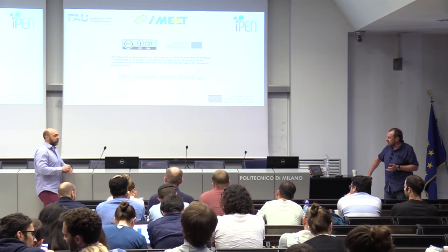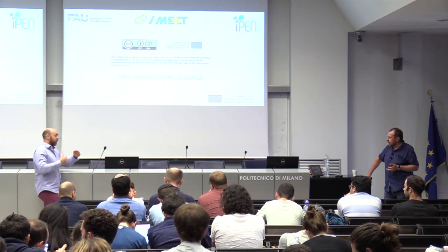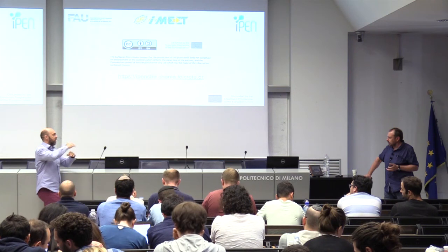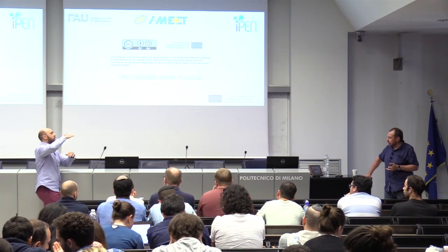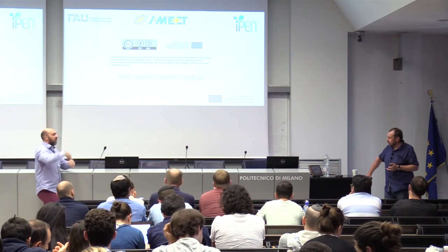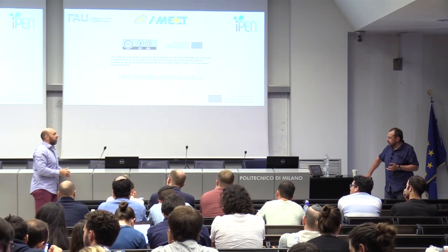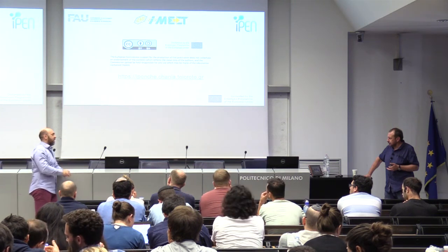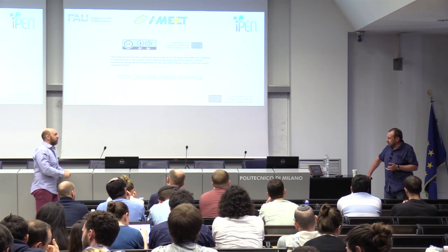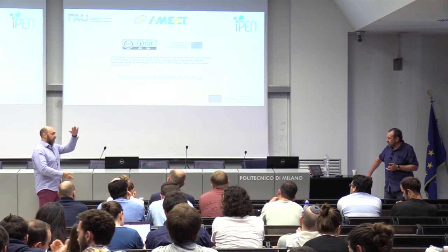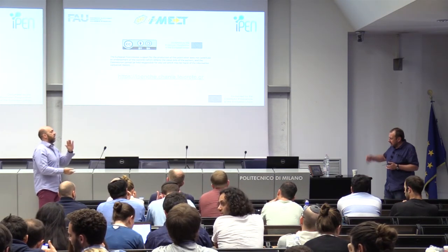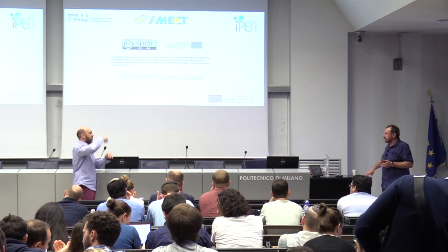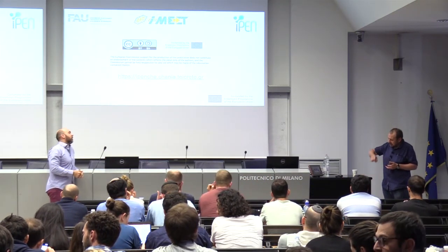Yes. The other thing that I would like to ask is, you have your electrode, you place your material, you do the P1, you place the other material, you do the P2, you place the top contact and you do the P3. Am I right? This is the process. There are other people that place all the layers and do the process when they have deposited all the layers. Is this possible in your laboratory? So they are not doing it in stages, but they deposit the transparent electrode, then the transport layer, the active layer, the electron transport layer, and then the top electrode, and then they do the lines. But then you have to be able to get into the structure.